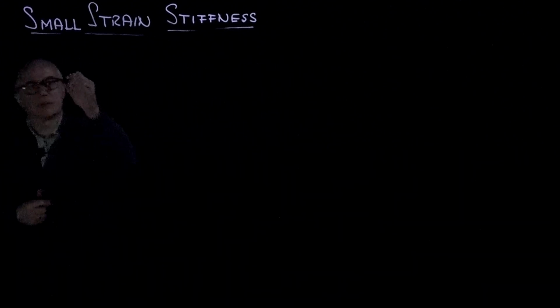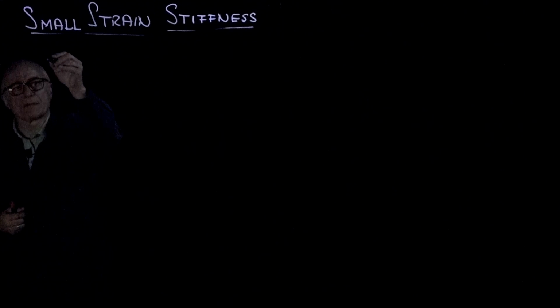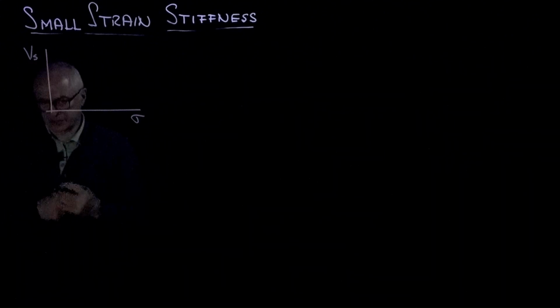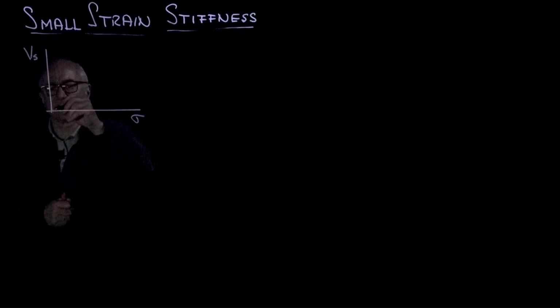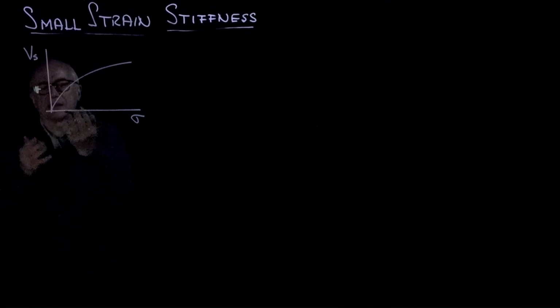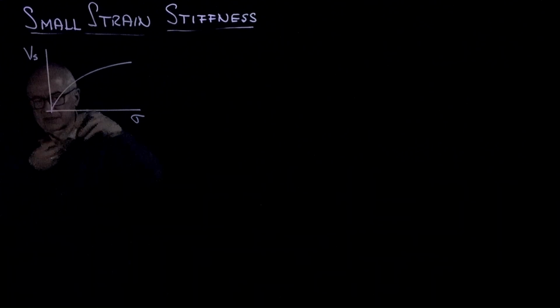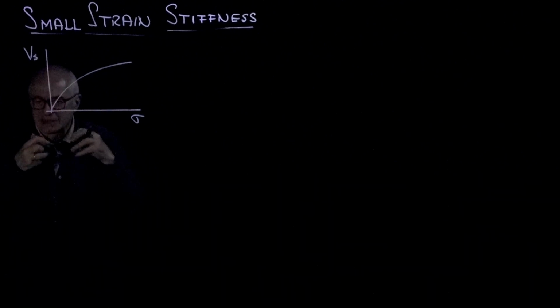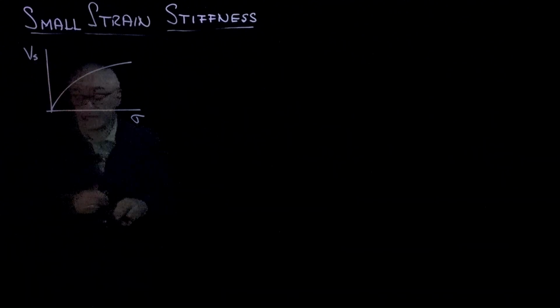It follows from Hertzian type behavior and the fact that the velocity is a power function of the stress, that if we plot that trend, which is the shear wave velocity versus the confining stress or the applied stress, this is typically the trend that we observe. Notice that there is basically no stiffness if there is no stress, because it's like particles. In the extreme case, you could be running this in the space shuttle. Particles would not be exerting any confinement against each other. There would be no propagation.